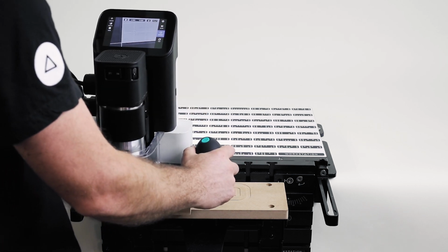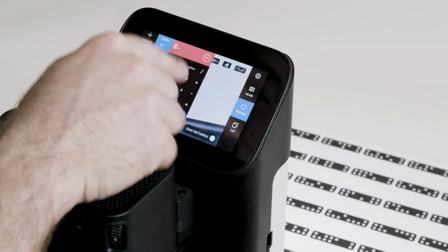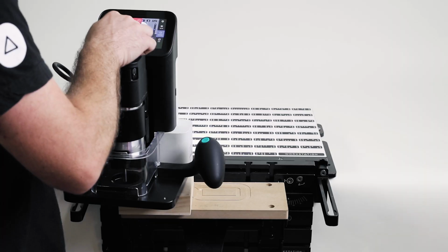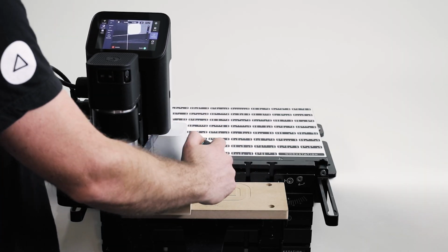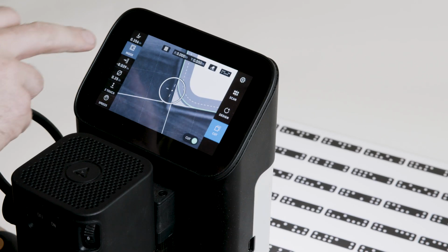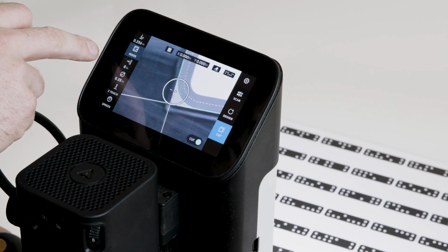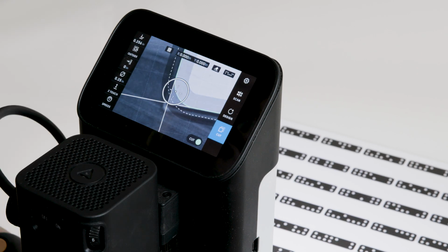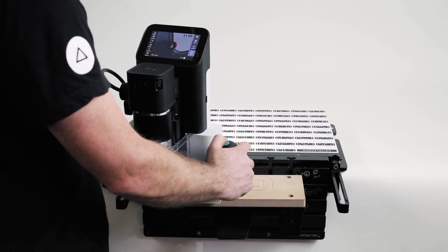So at 1/2 inch increments, I can go in and create a shape, 2 inch by 2 inch, 0.5 inch radius, done. So if I wanted to come in and round this corner, I can just do this right here and go to cut, no offset, and make that an outside cut. So I could then just round that corner. I'll do an air cut just to show you what I mean.